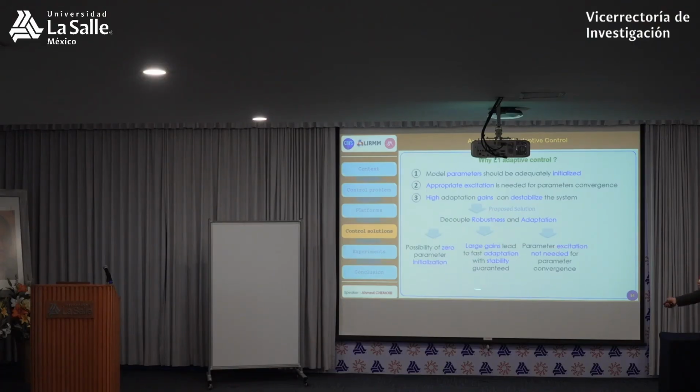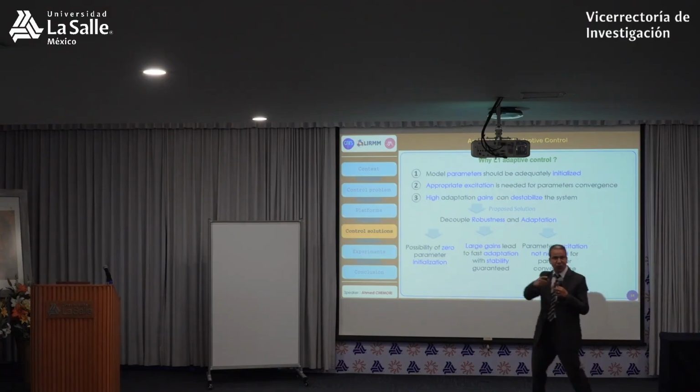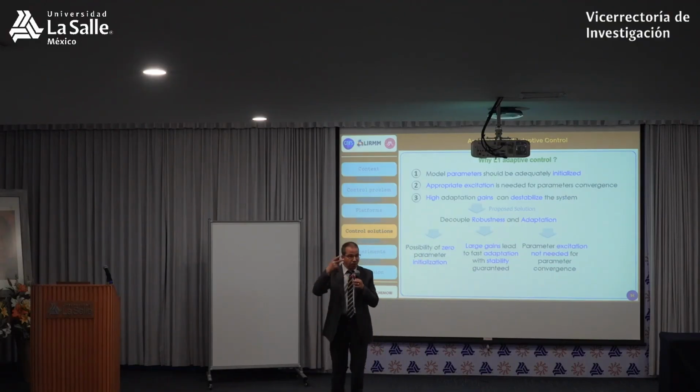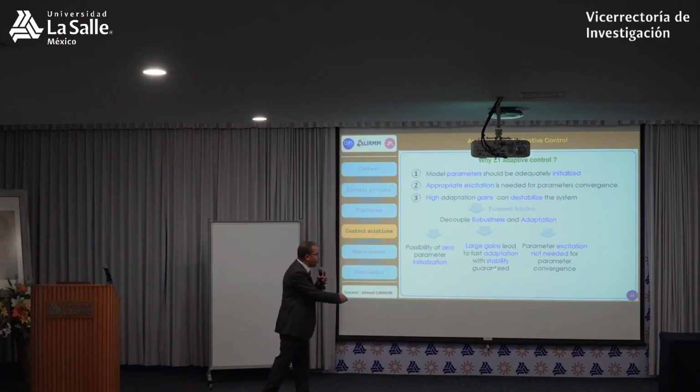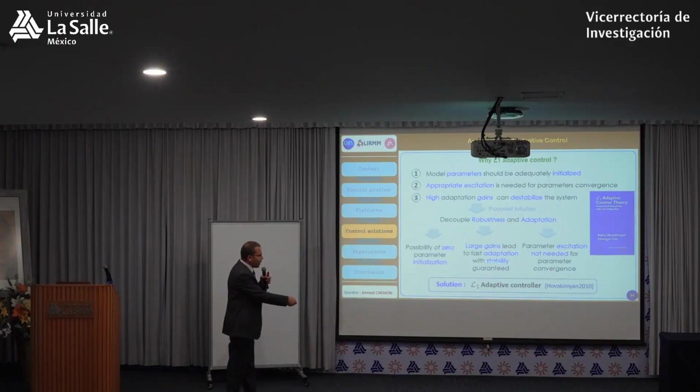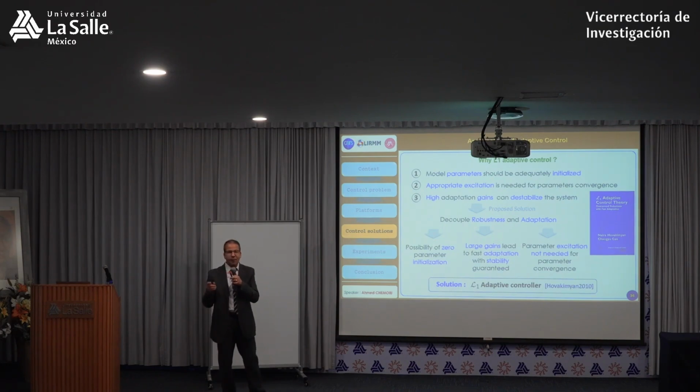The second consequence, I can increase the gains. There is no limit. I will not destabilize the system, I will keep the stability. Why? Because the controller is based on a low-pass filter that will filter the action of the controller. Even if you increase the gains, the control action will be filtered and it will be okay. There is no problem of instability. And the last consequence, you don't need parameter excitation. Simple trajectories should work. All these advantages we get from the L1 adaptive controller.